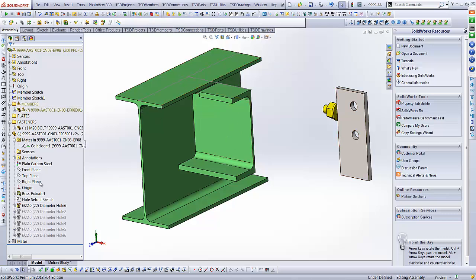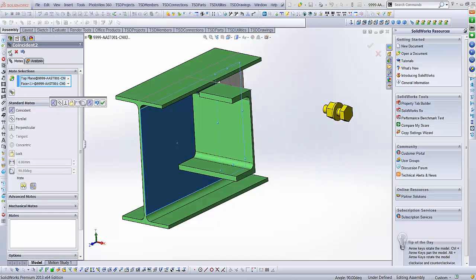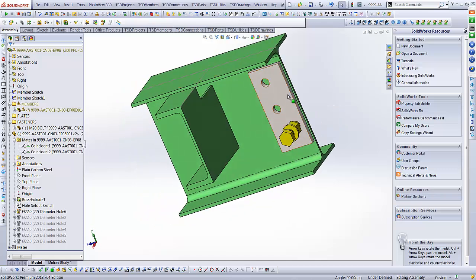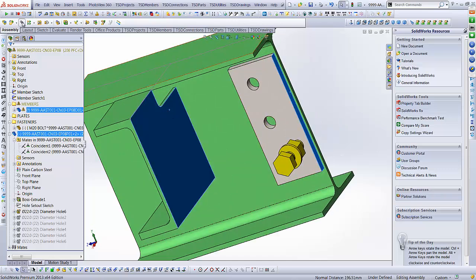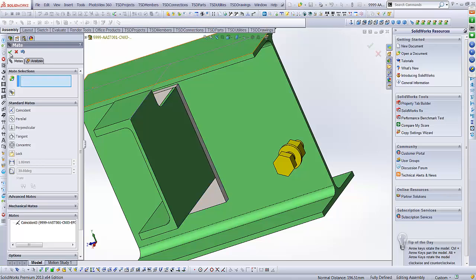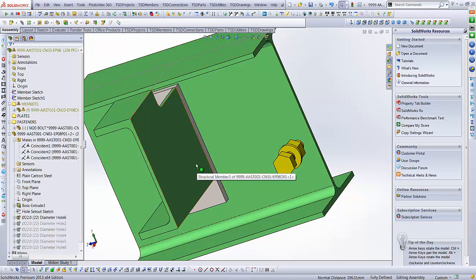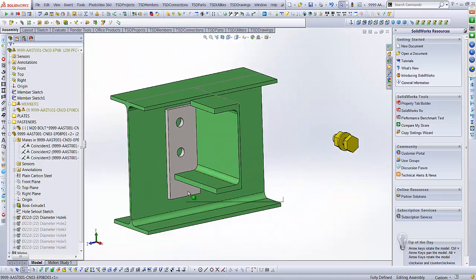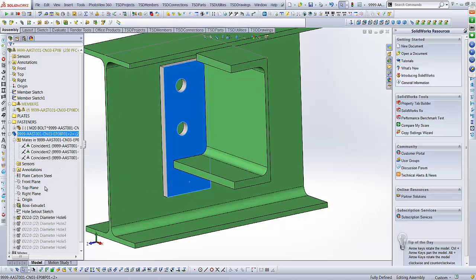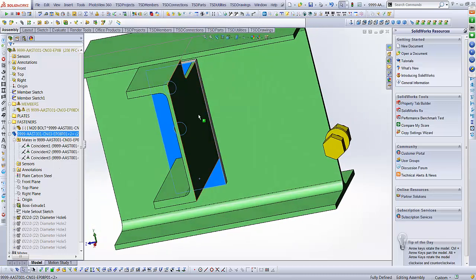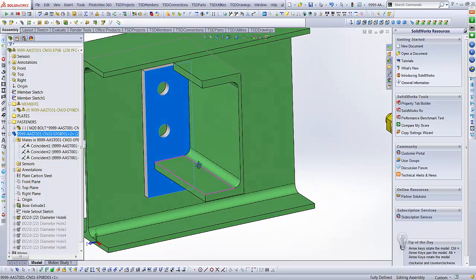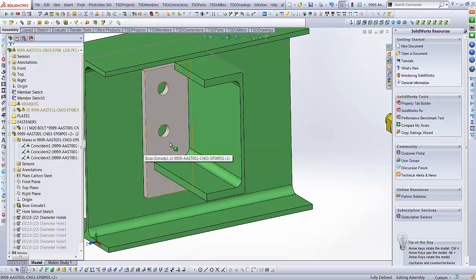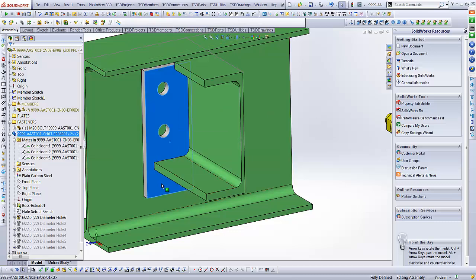Alright, now I'm just going to add that mate, which allows me to position it, and depending on your design and what your requirements are, I've made that flush, which means that you've got to do a bit of prep. It's a butt weld. A bit more prep involved in butt welds rather than fillet welds. You could extend that plate 10mm out off the back and allow a full fillet weld to go right round. Either way is fine.